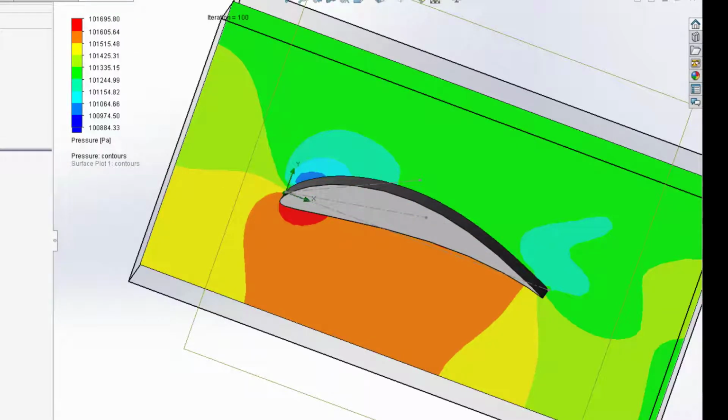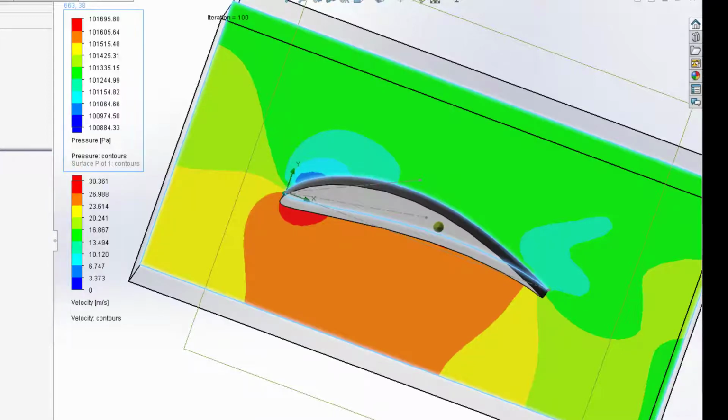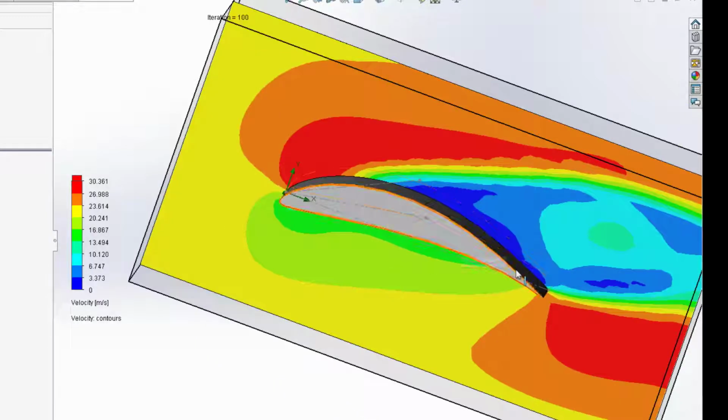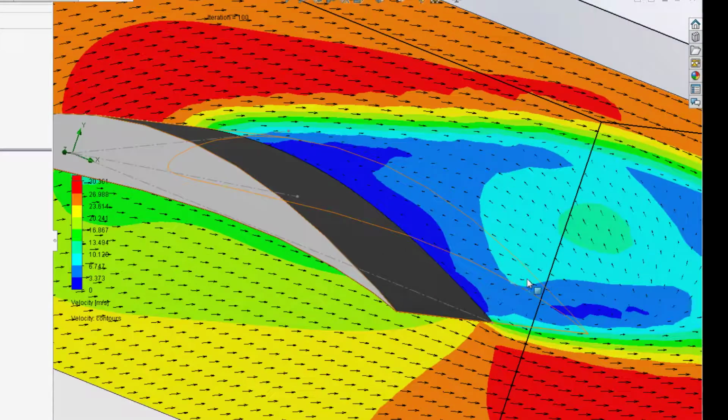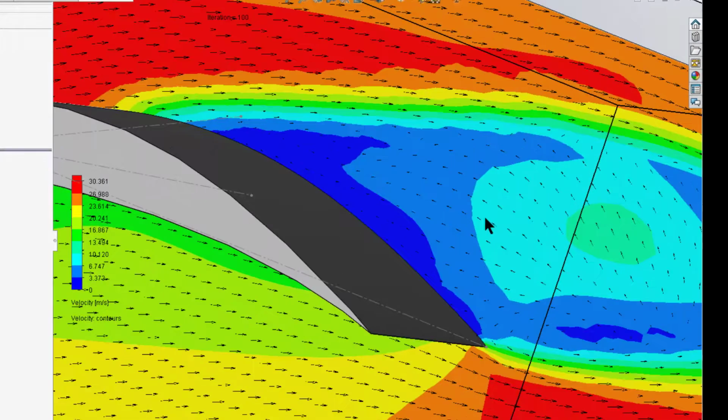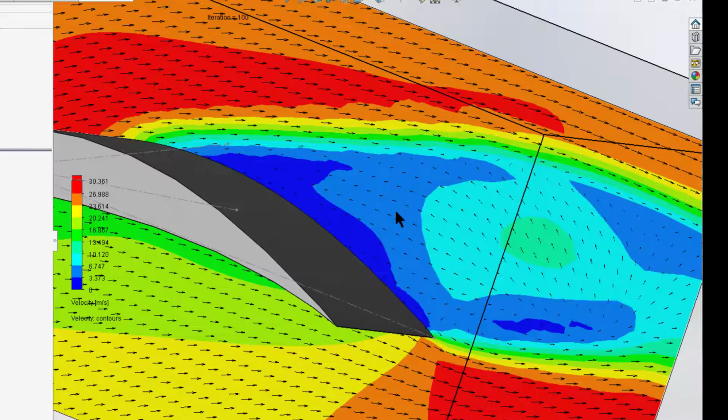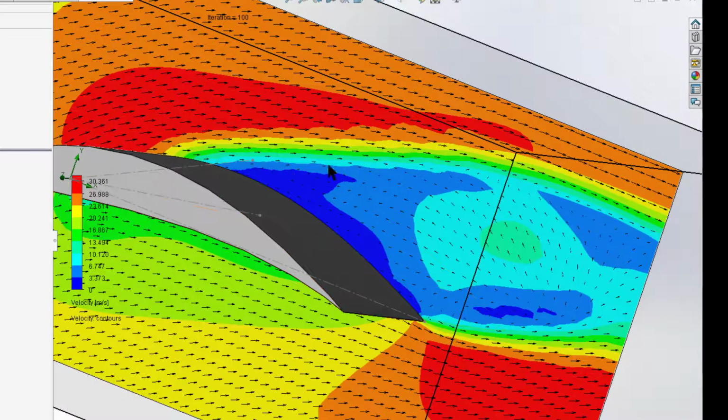And if I actually show my velocity and turn off my pressure, you'll see exactly that. Now you'll see in the ISO lines here, the vectors, you'll see that turbulent airflow, and you actually see the air going the wrong way. So the air is going forward as opposed to following the wing. So that's that big vortex and the huge vacuum that we're dragging along, all that induced drag, and that's why your string's picked up. So we're predicting that.